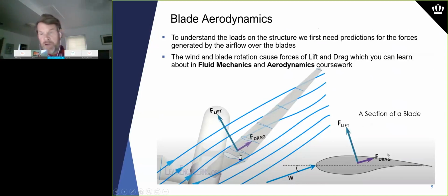So now we have this airfoil section, looks like a wing, right? And flowing over it. What does it do? It generates a force. So we get 2 forces, one called the force of lift and one called the force of drag. Okay, so the force of drag is going to be identified as parallel to this relative wind direction, force of lift perpendicular.